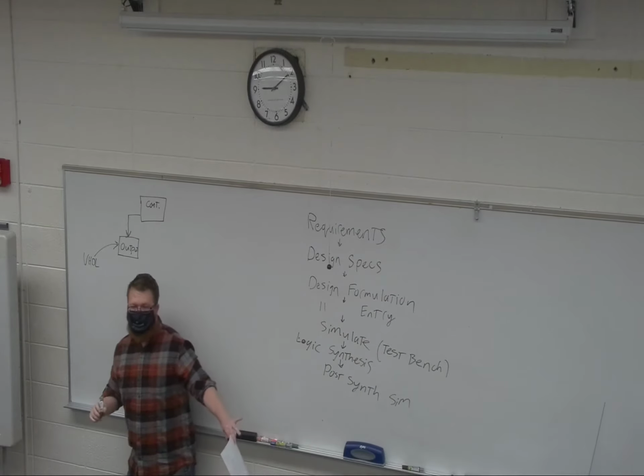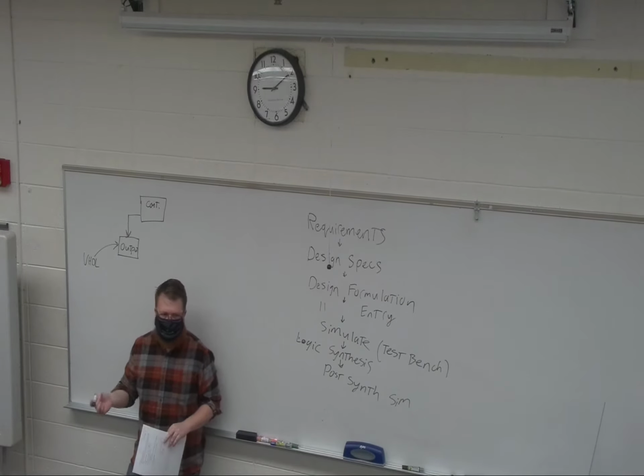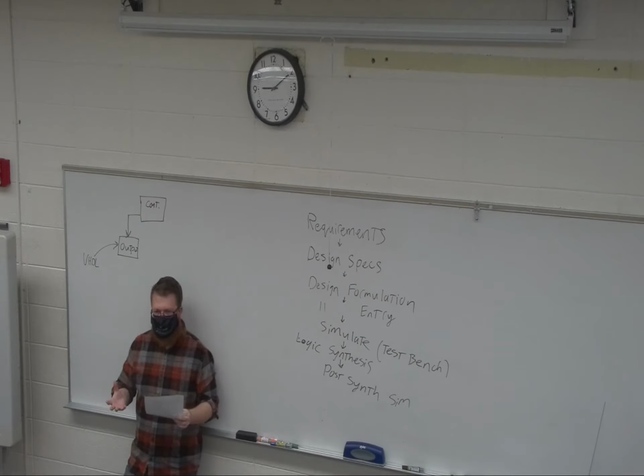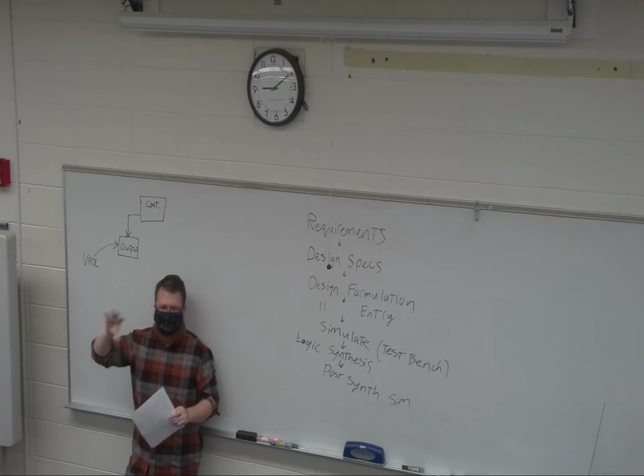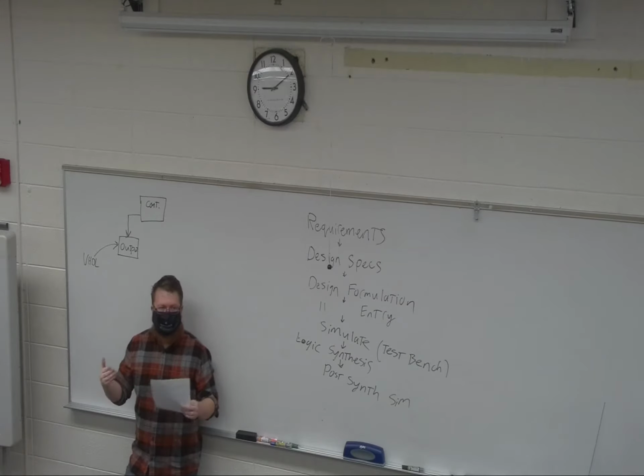You'll then move on to post-synthesis simulation. What this does is it goes, okay, I've used these devices and formulated this hardware, and now I'm going to use physics math to run the simulation. So rather than just logic progression, it is actually trying to simulate the results using the real devices. And that gets more accurate and is really important in high-speed design. But there are going to be other issues that we'll get into when you're actually coding that will explain why that matters.